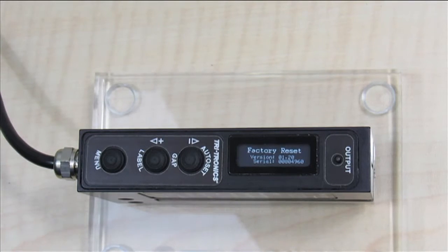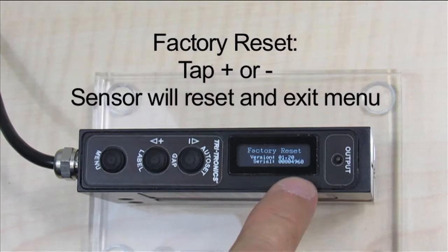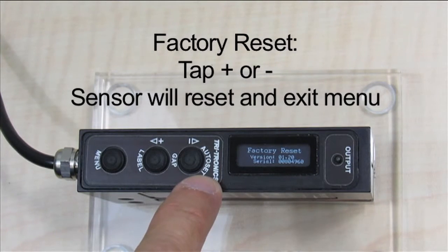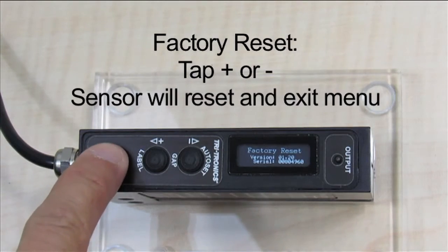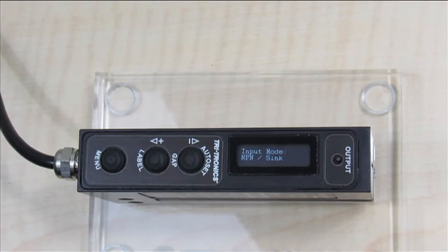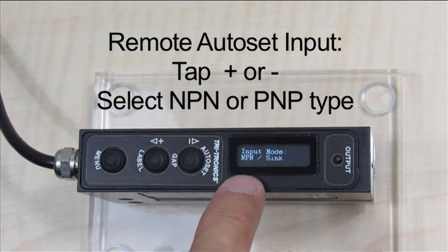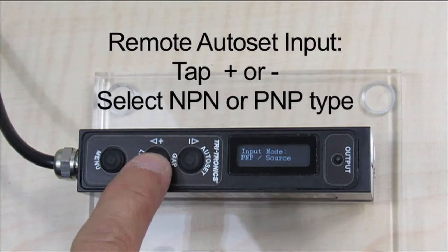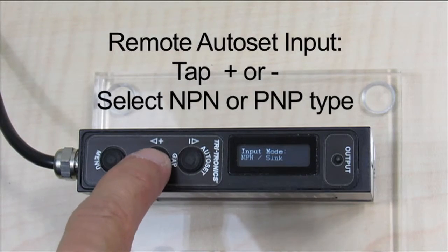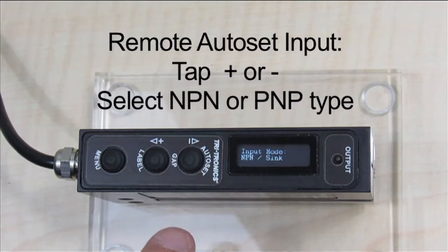The first option is Factory Reset. Tapping either the plus or minus button will clear the sensor settings and restore factory defaults. Tapping the menu button will advance to the next option. Input mode specifies the type of input the remote Autoset input will be. Tap the plus or minus button to toggle between NPN and PNP type inputs. Tap the menu button to advance to the next option.